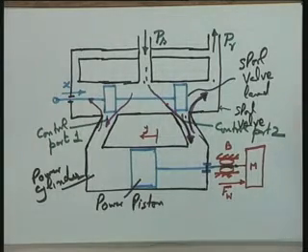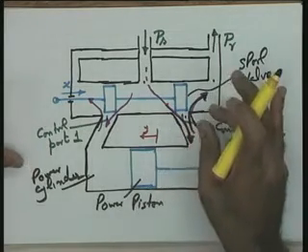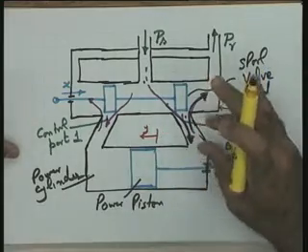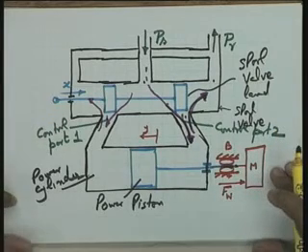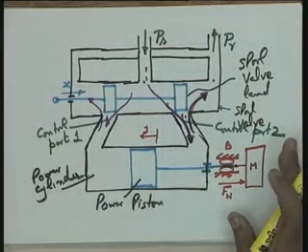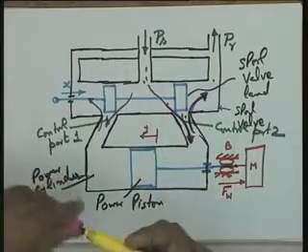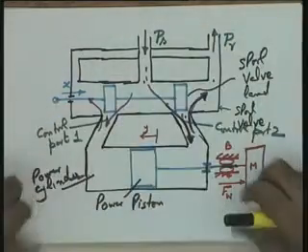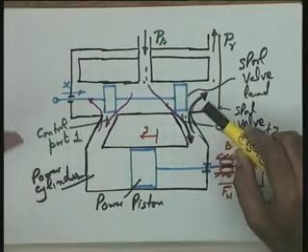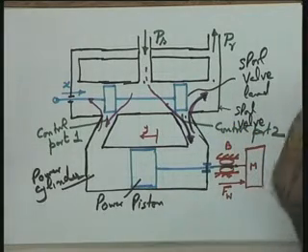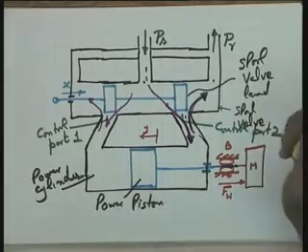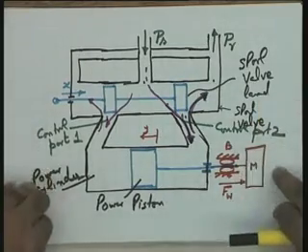And I am going to show to you how this condition is realized, that is how this particular requirement is met, that the leakage flow into is equal to leakage flow out of the power cylinder, right hand side chamber as well as the left hand side chamber. And to prove this to you, I will like you to recall the relationship of fluid flow through an orifice. You will please note that this is also a restricted fluid flow, and we have already seen in our earlier discussion that a restricted fluid flow is governed by the orifice flow relation, which is a non-linear relation.